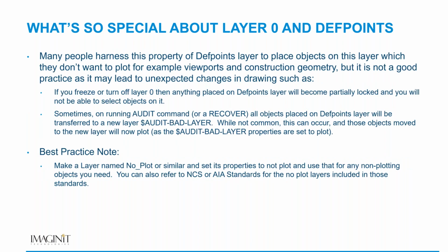So here's the big pitfall, and this is a lot of what I tell people. Many people harness the properties of the Defpoints layer to place objects on this layer which they don't want to plot. A common thing is viewports and construction geometry. A lot of people do it. It's a common practice. However, it's not a good practice as it can lead to unexpected changes in the drawing.